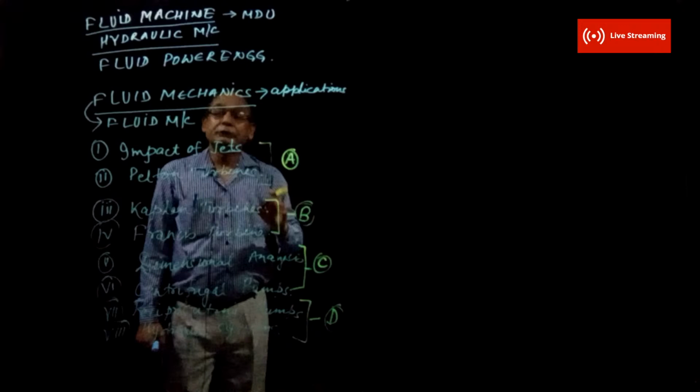Now Kaplan also, but the basic difference between Pelton and Kaplan and Francis, these two are reaction turbines. Remember, working principle will be different. These two are based on reaction and this is based on impulse. So working principle changes. There also we will be studying in Kaplan turbine what is their classification based on heights, how do they work, what are their construction details, what is their output.